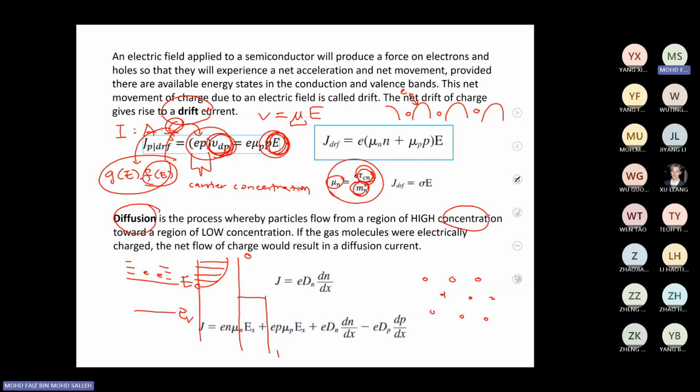By inserting another type of atom, or by doping. For example, silicon. If you want to make it an N-type material, you want to increase the number of carriers. You will dope the silicon with phosphorus. Silicon has 4 valence electrons. When it makes bonds to form a silicon lattice, each atom will have 4 silicon neighbors, right?